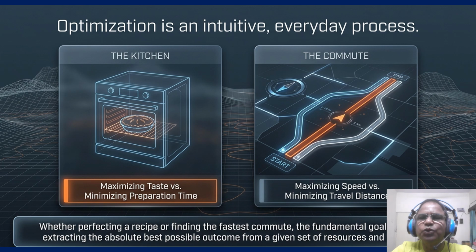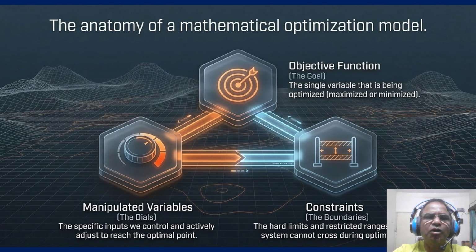If we reduce coke too much, as all operators know, the furnace may become unstable. If we overcorrect the burden, cost also goes up. So optimization means finding the best balance within the cost and without deviating from the operational norms.